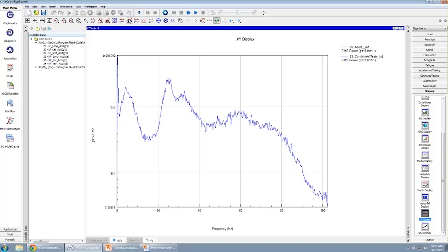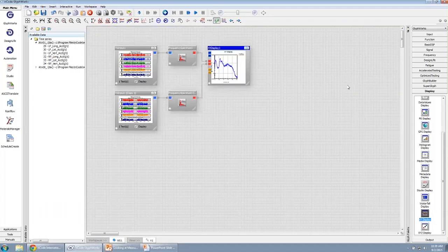This goes to show that we have lost the concept of time when we go into the frequency domain, and if we repeat that same test over and over, all we're doing is increasing the number of buffered time series events that we look at the frequency content of, and they're all the same. So if we average them, we're going to get the same kind of information.